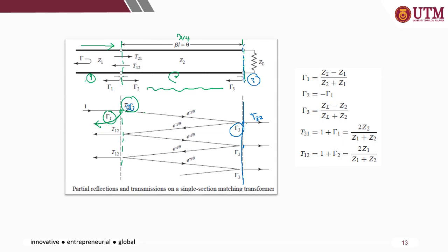So you can see that the reflection coefficient and the transmittance value are very dependent on the element connected to it. The reflection coefficient and transmittance from one section to another can be estimated by the following equations, which depend on the characteristic impedance at each element. So Z1 at the earlier point, or at transmission line 1, and then Z2 inside element 2, and so on.